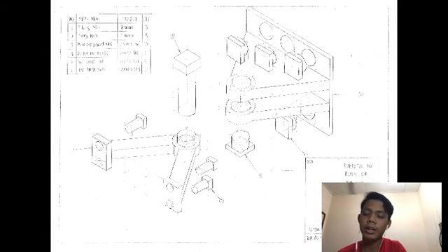Alright, the last one is the exploded drawing. We see several screws that connect three main components to complete the aileron mechanism. The first one is the M5 x 0.8 socket head screw, which is the connector between fitting 1 and the aileron. This screw has a quantity of 30 in this mechanism and is made from stainless steel.